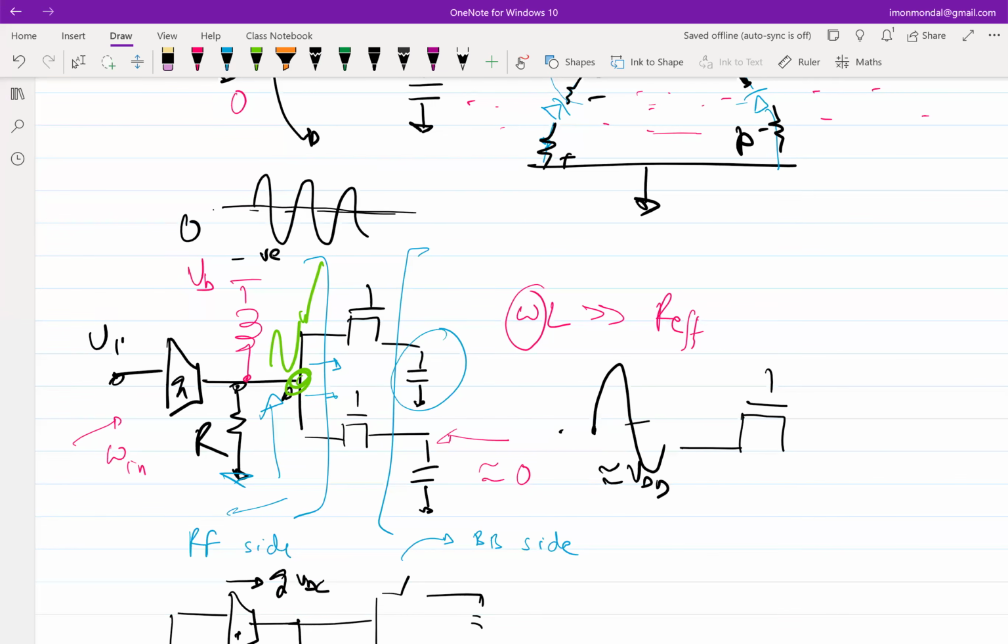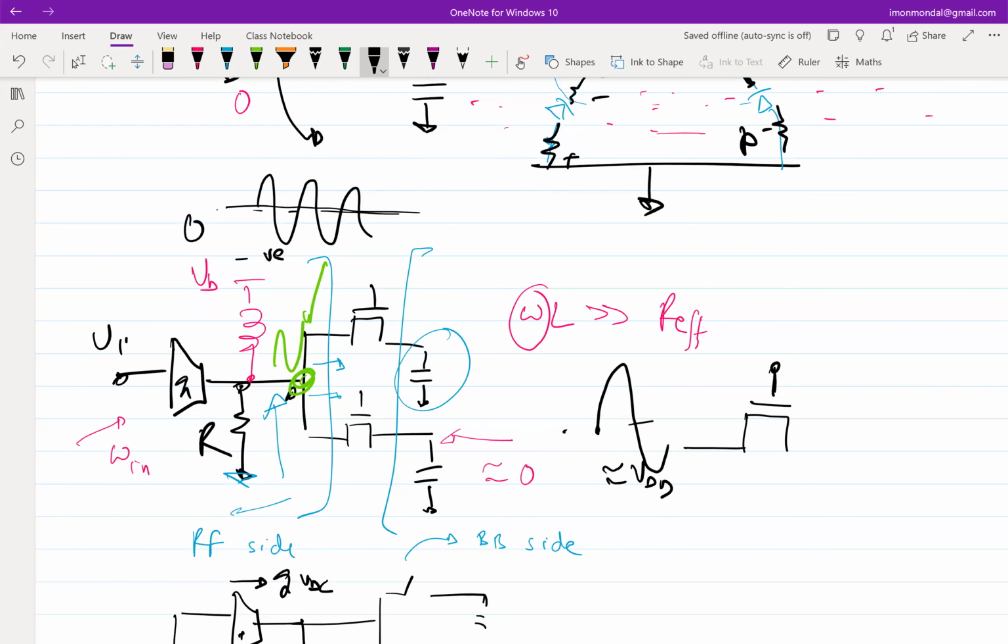Because the switch, this voltage that can go maximum is how much? It can go VDD, right? Maximum you are driving with a square wave, this can go to VDD. So naturally, when this goes above, if this is, let's say, VDD, so clearly, even if I assume threshold voltage to be negligible, which is definitely not the case, this guy is getting clipped off. If I take threshold voltage into account, then maybe till here it is getting clipped off, right?